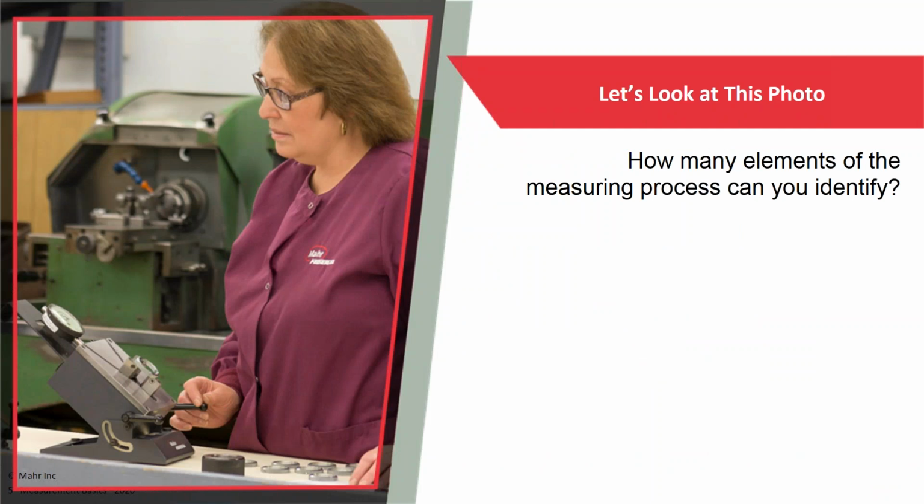So take a look at this picture here. This is a typical measuring process that's happening in a shop environment. How many elements of the measuring process can you identify? Let's see what we can find. The first one down the bottom there is the standard or the master. This could be a master ring, a master disc, a gauge block, some reference standard. The second part of the measuring process is the workpiece, the piece that we're actually trying to measure and find the dimension of.